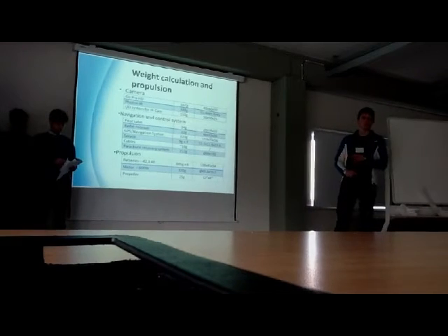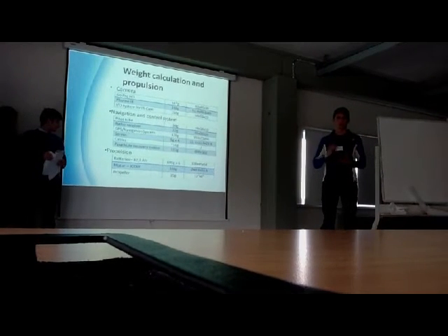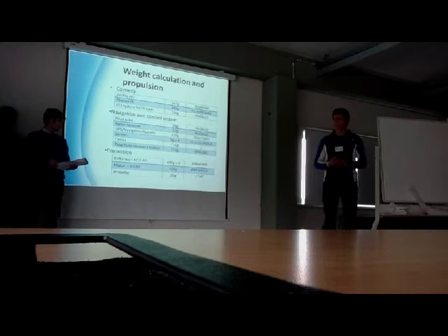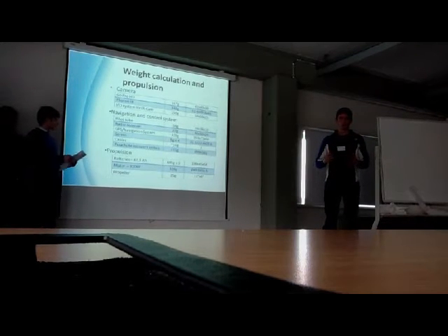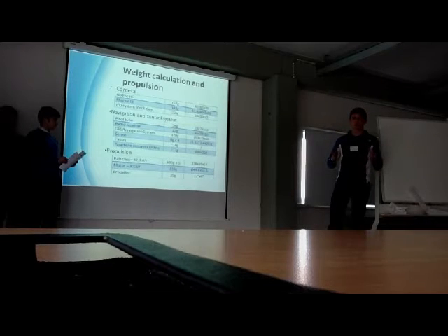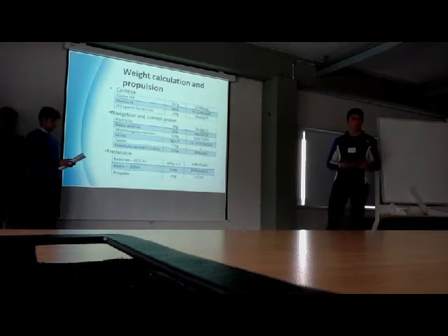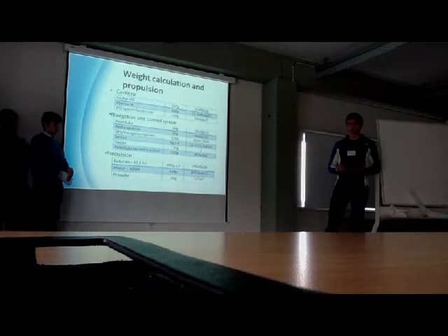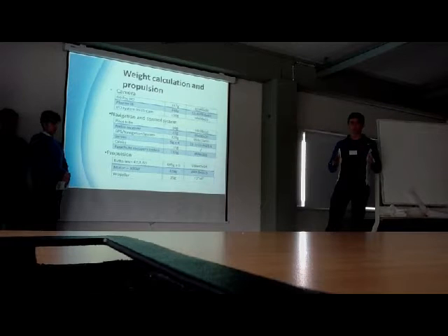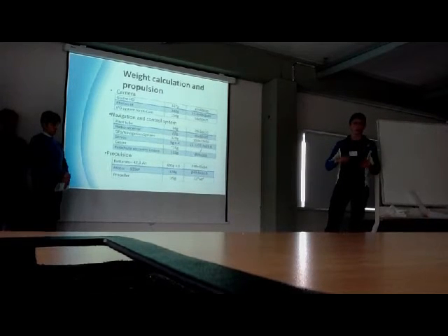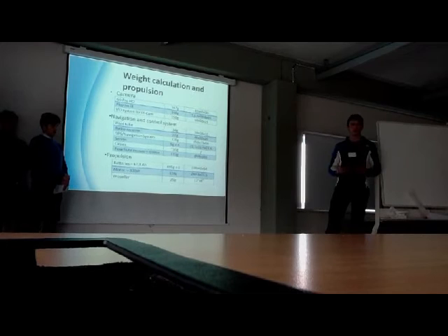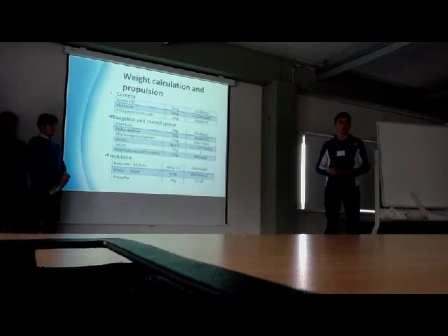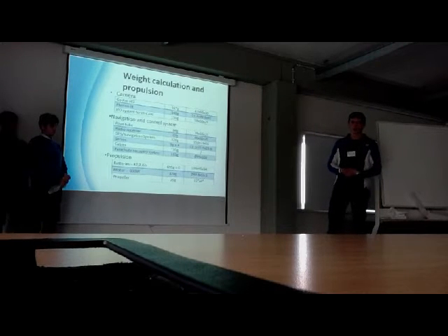Yes, because here is a place where we have one of our first and biggest problems, the autonomy of the battery. So we made the first calculation with the idea of a mission of 2 hours, so a flight of maybe 2 hours and a half with landing and takeoff. At the beginning we wanted an aircraft that was less than 5 kilos, and with the first calculation, we saw that we needed, I think, 13 kilos of battery to fly 2 hours. So we had to find a solution.